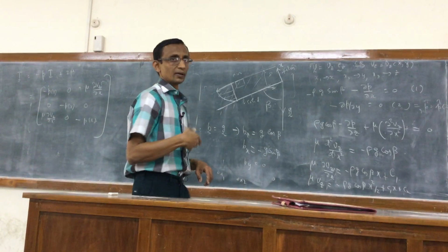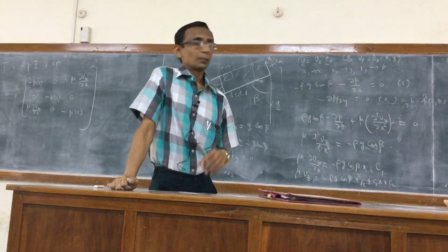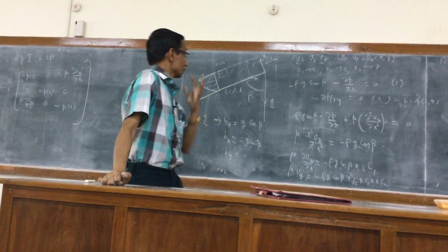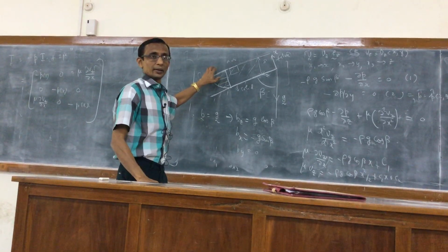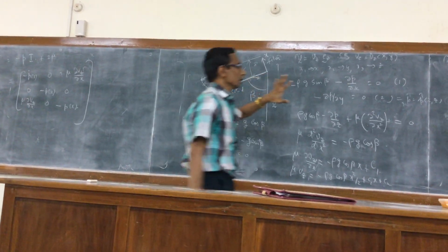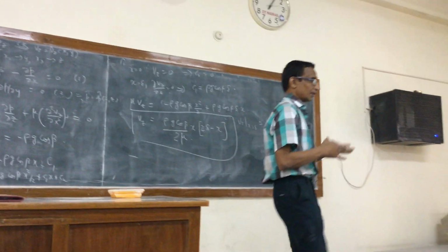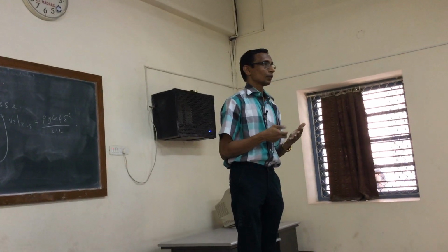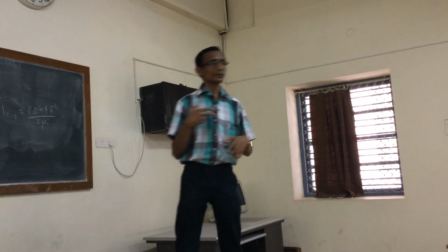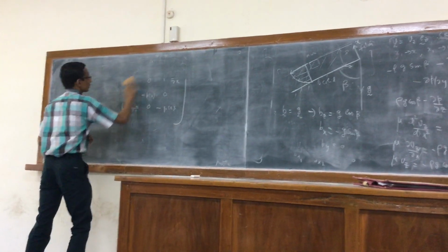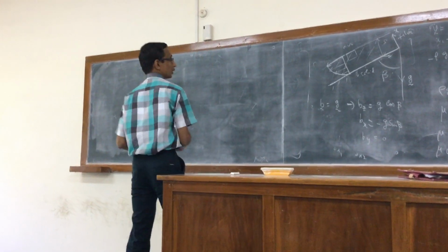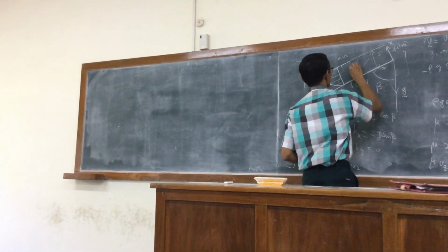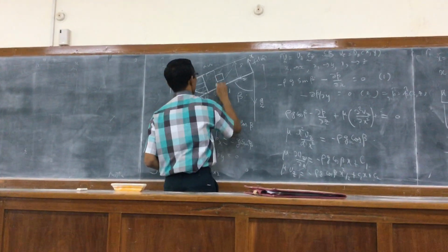The shear stress will have the opposite behavior. The shear stress is actually maximum here, it can be easily shown. It actually becomes 0 at the interface. It will be a good exercise because we have the shear stress tensor, but what is actually of interest is the way the normal and the shear stresses act on the fluid at any point within the fluid.